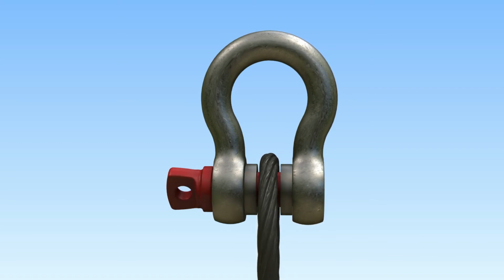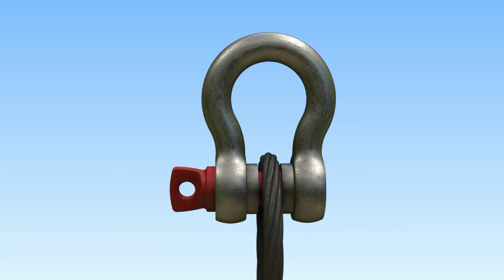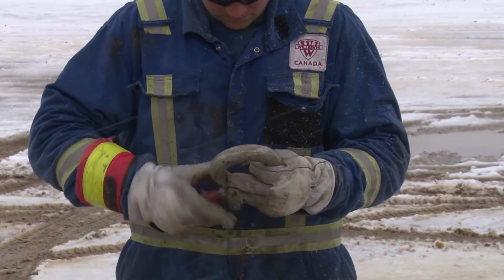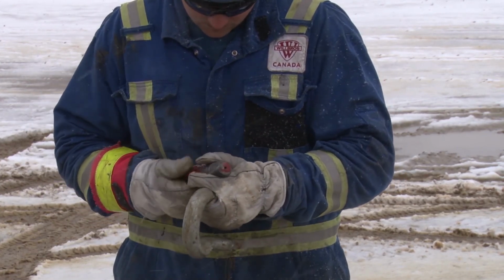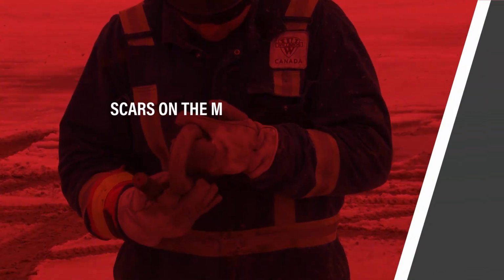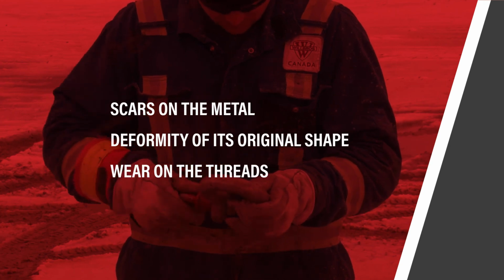If the wire rope could roll against the pin and unscrew it, prevent the pin from unscrewing by threading a wire through the pin's hole to the shackle body, and consistently check all shackles for damage and replace them if any issues are found that compromise the integrity of the shackle, such as scars on the metal, deformity of its original shape, and wear on the threads.